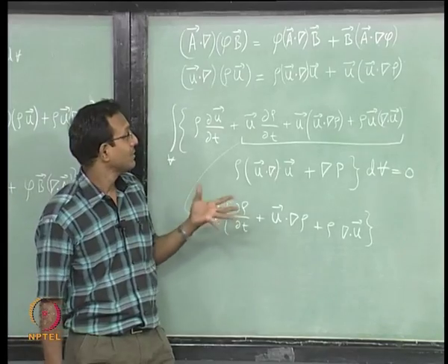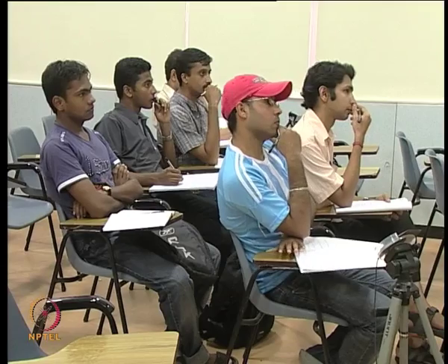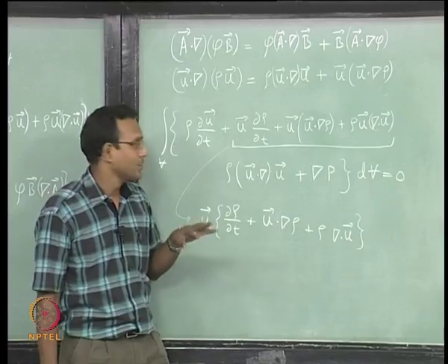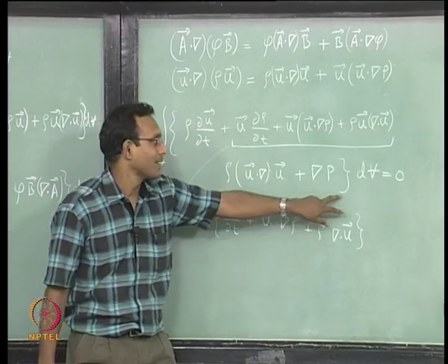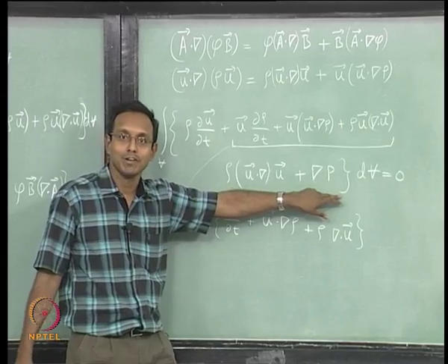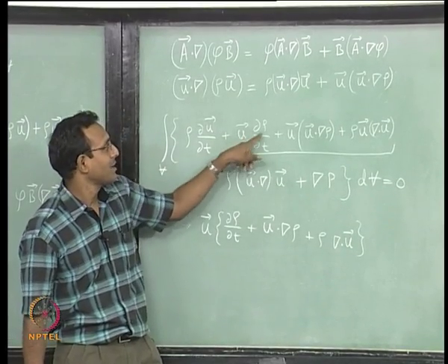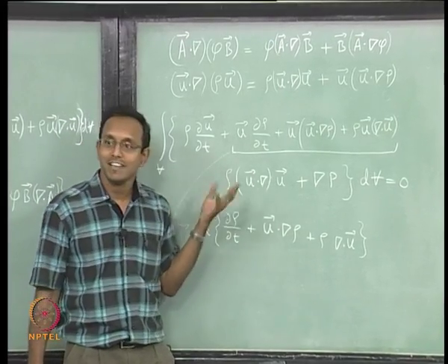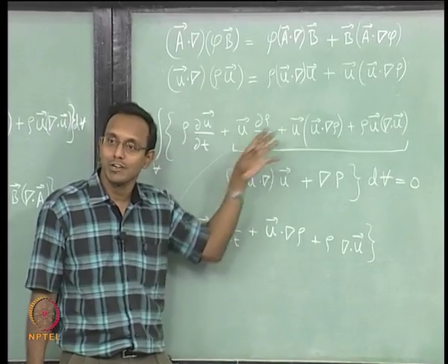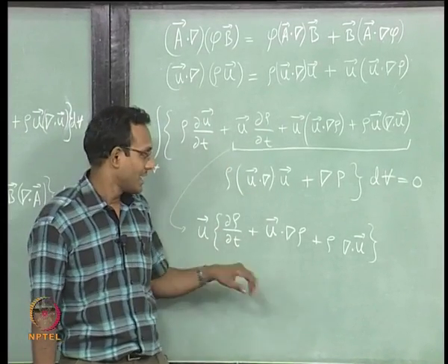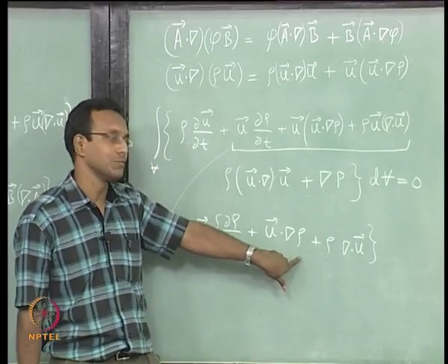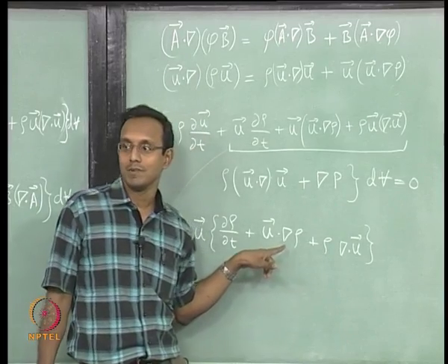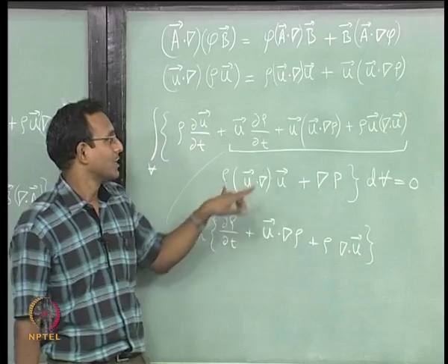So if we look at the original expression for the momentum equation, if I do not use this simplification, the actual momentum equation is this, whatever is inside this bracket equal to 0. If I look at it that way, I have this ∂ρ/∂t term. So in theory, density variation is also taken into account, except I am simplifying this expression using the mass equation, because the mass equation is also satisfied in my flow problem. Mass equation and momentum equation are both satisfied, so I will simplify this.